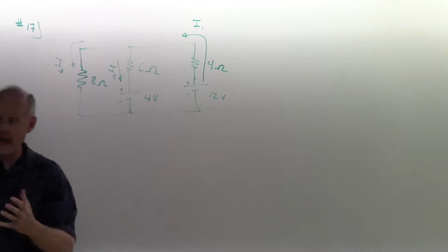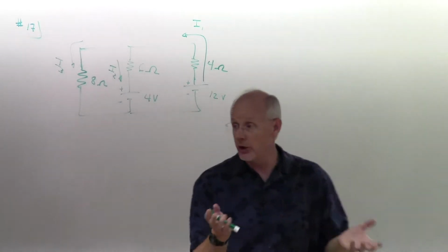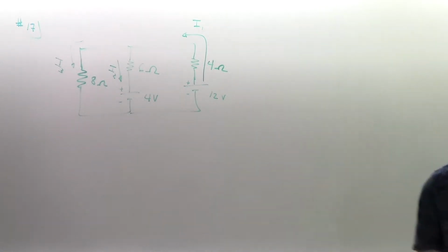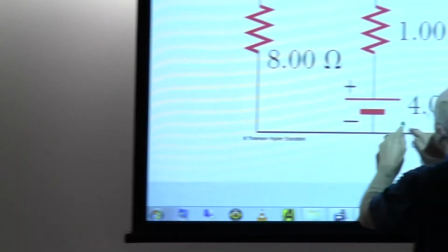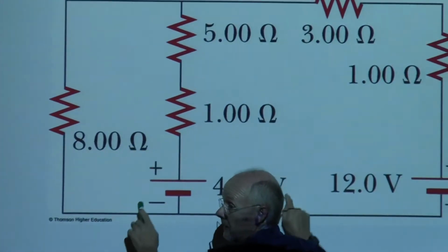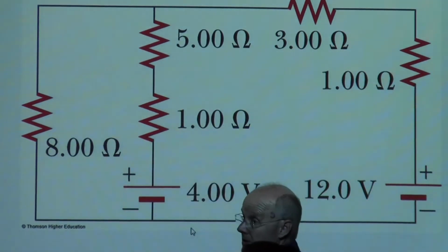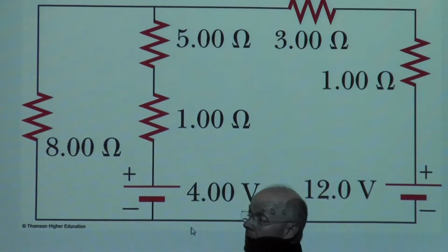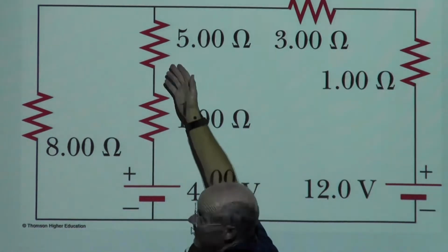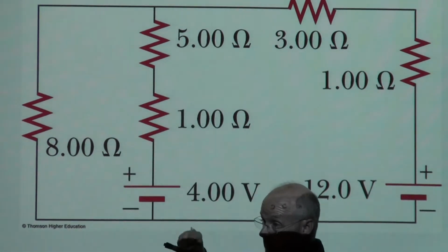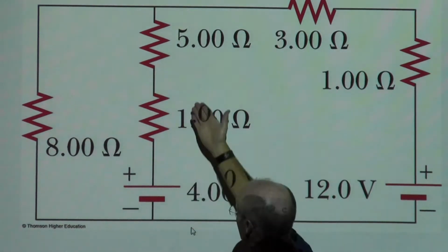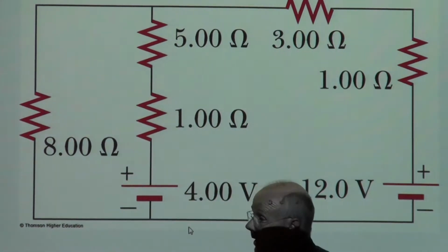So it's either, A, assuming these are really good, new batteries with no internal resistance, or if you look closely, I would wonder if the author isn't really saying this is the battery, where the battery is made out of the EMF and the internal resistor. And that's where this 1 comes in. And then the 5 is external, part of your charging electronics, so that we don't shove too much current through it at one time.